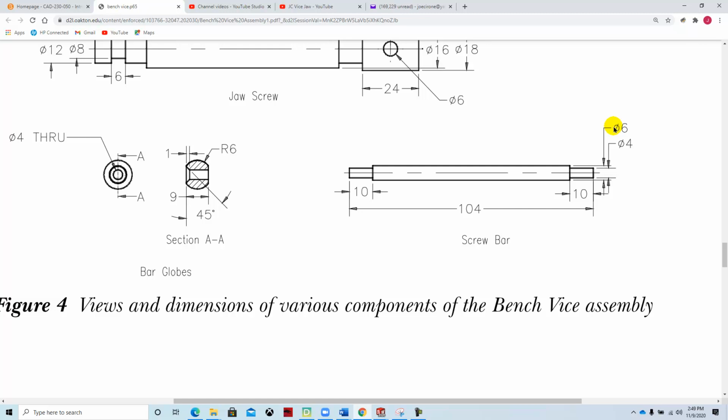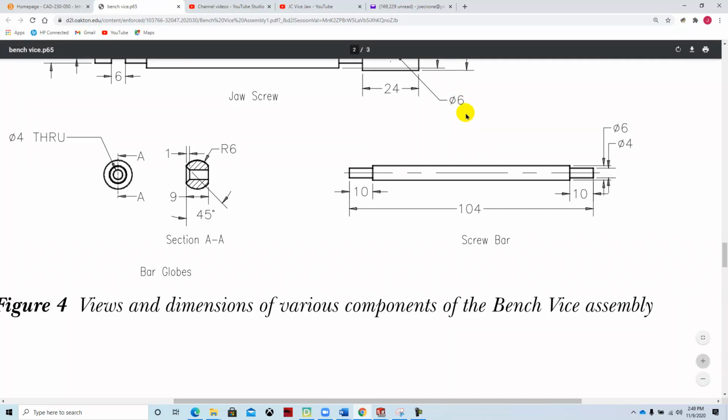It won't slide into that hole. So the machines are very precise, and typically I make holes a 32nd oversize to have some clearance. So we could make this maybe an extra 10 thousandths,